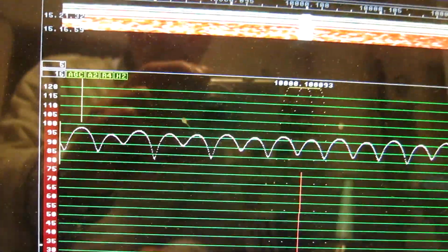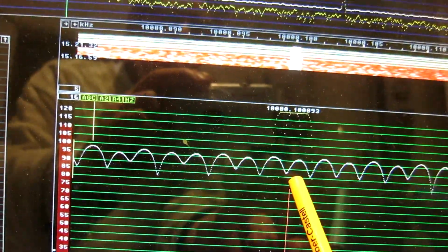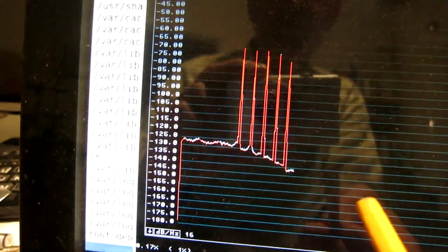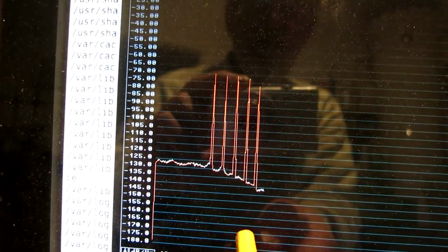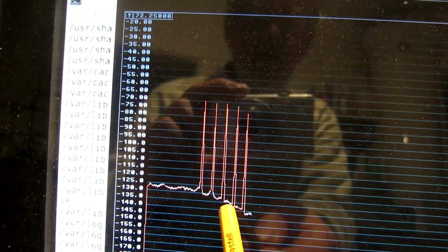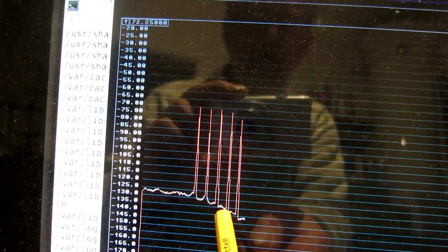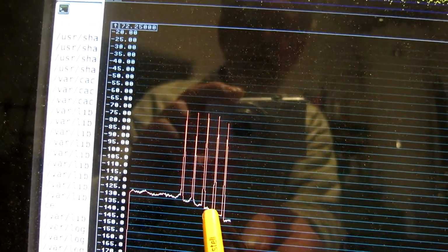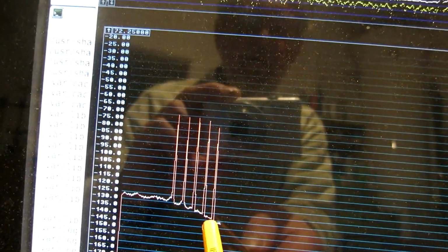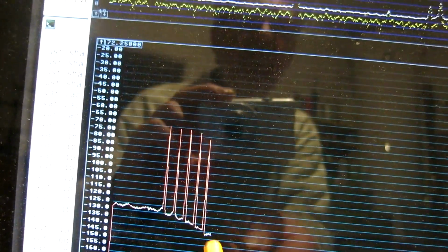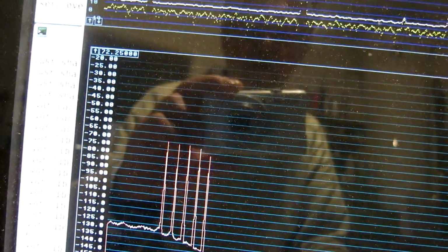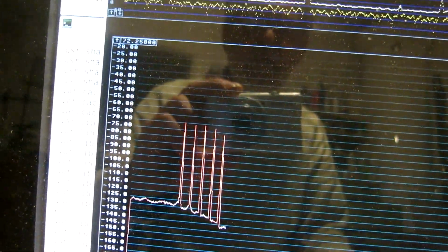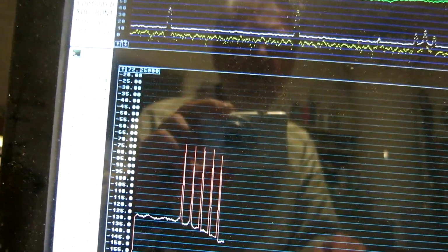And the 50 Hertz spur, you don't see it in the spectrum, but we do see it in the signal evaluation. It seems to not drop immediately, but after a power reduction it goes down a little bit. But here it behaves differently. And I will look at it at even lower levels.